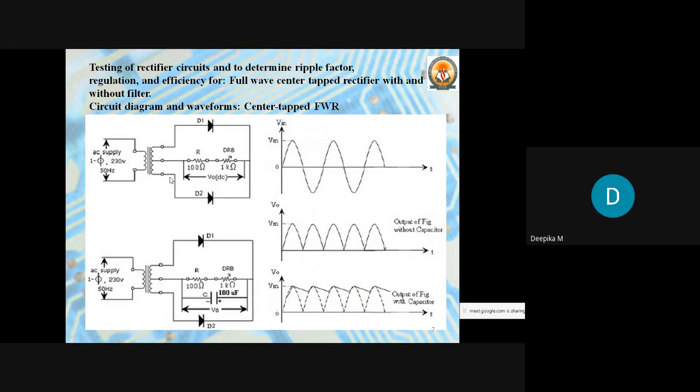Therefore the step down transformer is used, and this is a center tap transformer, because in the secondary it has a third terminal at the middle turn. If it has 5 turns, the third turn will have the center tap terminal. So this is the center tap transformer.